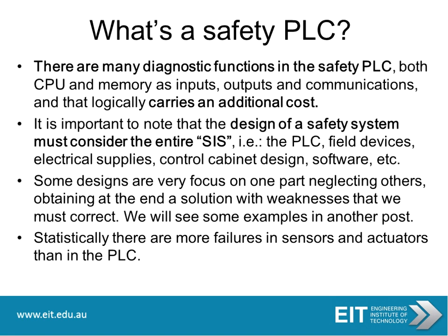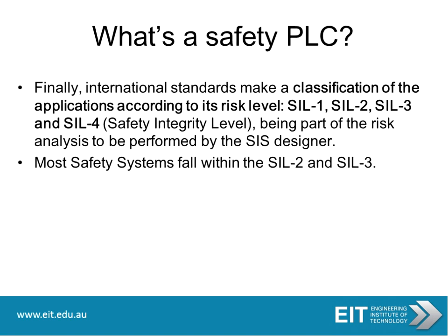And it's important to note that the design of a safety system must consider the entire SIS: the PLC, the field devices, electrical supplies, control cabinet design, software, etc. Some designs are very focused on one part, neglecting the others, and obtaining in the end a solution that has weaknesses that must be corrected. Now, statistically, there are more failures in sensors and actuators than actually in PLCs.